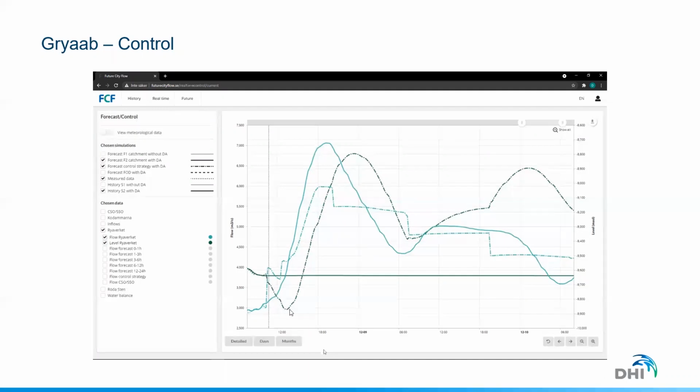The pump starts and the flows will go. We empty the tunnel and we can keep the flows into the treatment plant below this threshold here. And we actually manage, by using this control strategy, to keep a very good margin up to the first critical discharge point.